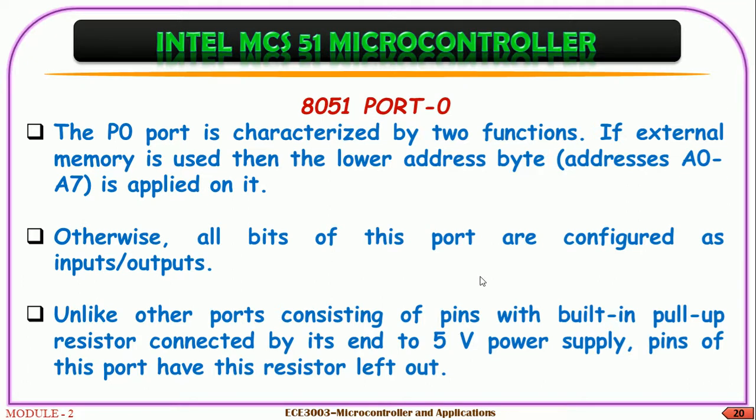Port 0 is characterized by two functions. If external memory is used, then the lower address byte is applied on it. Otherwise, all bits of this port are configured as inputs and outputs. Unlike other ports, whose pins have a built-in pull-up resistor connected by one end to the 5-volt power supply, the pins of this port have this resistor left out.